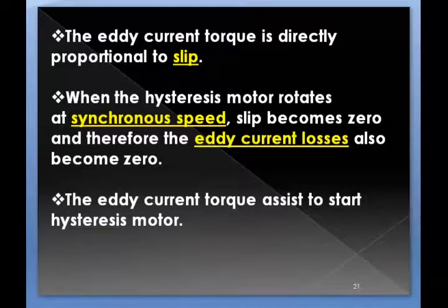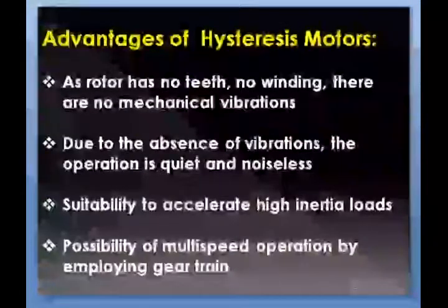When the hysteresis motor gets synchronous speed, the eddy current torque will be 0 and only the hysteresis torque is present and runs the motor. The eddy current torque assists the motor to start.